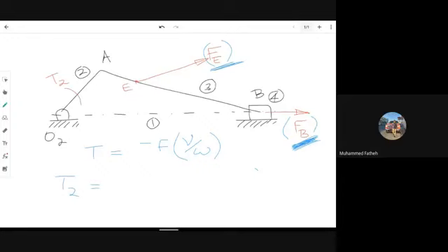Correspondingly the value of linear velocities will also change according to the force. That means I can write, since Fe is greater in value, 6000 Newton, I am writing that particular term first, minus Fe into corresponding Ve, minus of, in place of the other F I'll write Fb multiplied by the corresponding linear velocity value Vb, whole divided by angular velocity, which is simply one value, because the link number 2 is the link where torque T2 is acting and the angular velocity corresponds to that link.